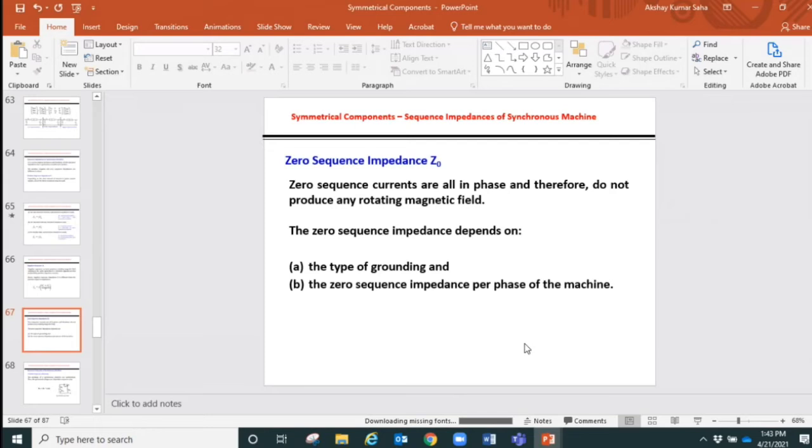Not only this type of configuration, meaning leaving it floating or connecting the neutral and the ground using a piece of wire for which the impedance can be neglected. We can put an impedance in between, or we can put a transformer in between the neutral and the ground.